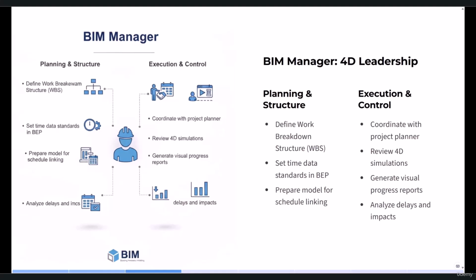So right now, let's go for the BIM manager in the fourth dimension. So the BIM manager should define the schedule structure of the project. WBS, or work breakdown structure, means breaking the project into different parts for management. In fact, projects will be divided into different items. Let's assume that we are just constructing a very usual building. So at first, we should define the project at the highest level in the name of the building, and we can say this building gets divided into different parts, so we have to divide it into different levels or stories.